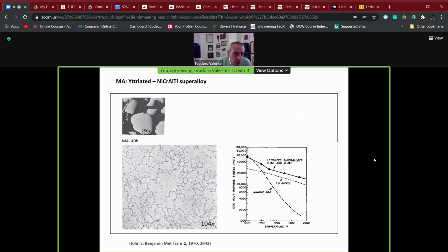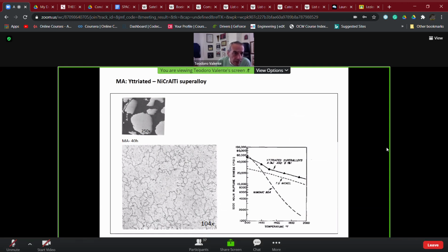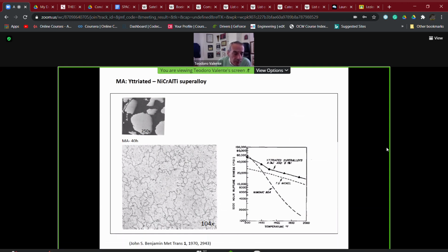So in order to have a mechanical alloy with this purpose, we need to put inside our mill yttrium oxide powders and nickel-based superalloy powders, and then we have the two mechanisms that we have described before, that is alloying and definition of the final average diameter of the alloyed powders.